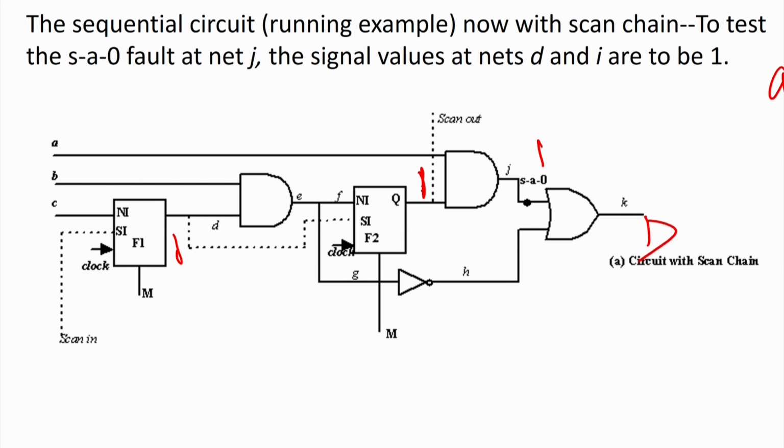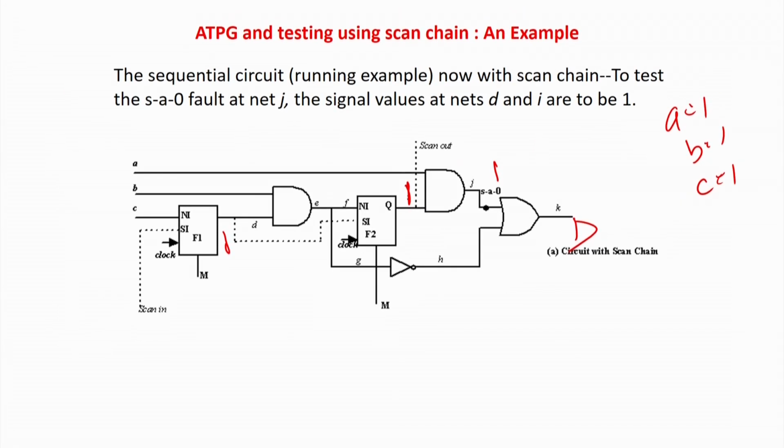Next, to make the second flip flop value equal to 1, you have to apply B equal to 1. So now if B equal to 1, this is 1, already D is equal to 1, apply a clock pulse, the output will be 1. So 2 patterns will be extra required to settle the business of the 2 flip flops in chain. If there are more number of flip flops in the chain, this problem will actually blow up. That you have to find out extra algorithms. In fact, people have already tried it.